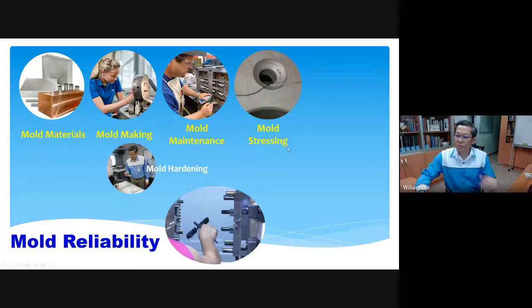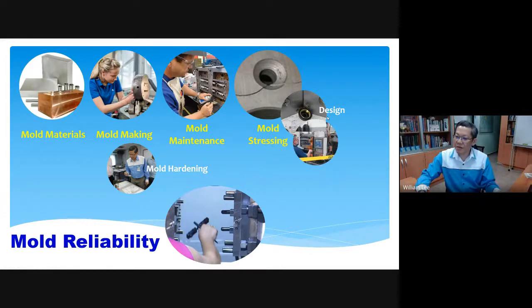And then how do you stress the mold? The stress level depends on the design of the mold. If you have a stress riser, a high stress point, of course, you can shorten the mold life. It also depends on the setup. If you have a misalignment, that is also no good for the mold to last longer. And it depends on the material. Some materials may have glass fiber added, which gives a high abrasion rate, so the mold will wear off faster.